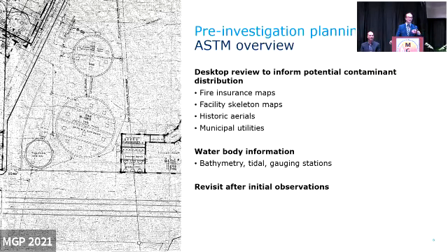There's a wealth of information out there about the water body typically, especially if it's a navigable water body related to the Army Corps or other permitting agencies, and you certainly want to get as much data from them as you can, to either not have to collect certain data like bathymetry or just inform your conceptual site model. And one thing that I've been pushing for as of late is to really revisit all this work after you get your first round of investigative data in-house.